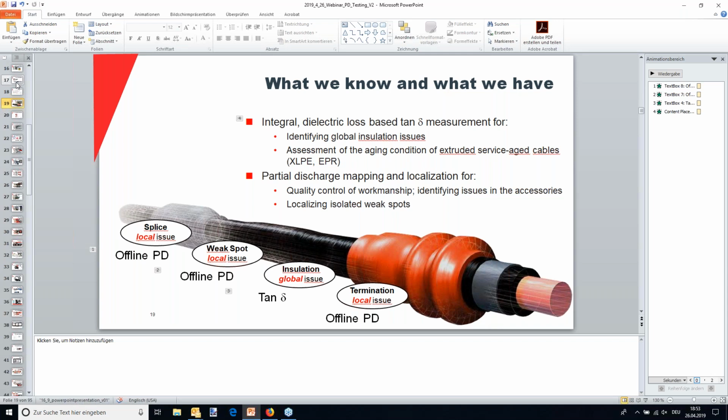So in talking about our products in this case, but the methods behind that, a PD scan is really a small device for medium voltage switchgear. That's predominantly the application. It has various accessories, test sensors, transient earth voltage sensors. It has the acoustic parabolic. It has the capacitive sensors and all of these sets. And that is mainly for medium voltage switchgear, fairly low cost to keep it attractive.